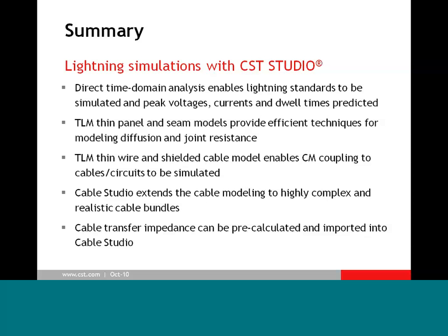There's actually been a lot of interest in that from customers over here in the USA, so I gather there probably could be similar interest in Europe, but it seems that in many cases the cable transfer impedance is unknown, and folks need some way to try and estimate those impedances. So I think we have a nice workflow for calculating that, but also for, in the 2011 release, importing that data into Cable Studio and then applying it to your lightning model.